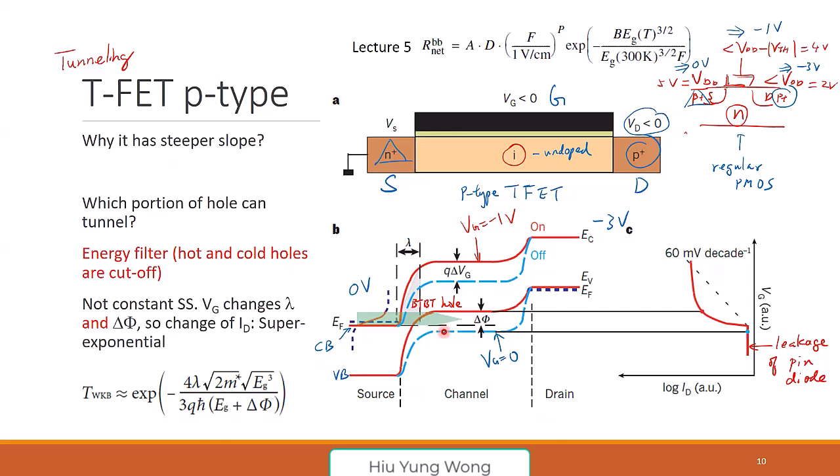Well, there's an electric field. Yes, electric field, exactly. Let's assume the electric field is also very high. Do you have band-to-band tunneling in this case? I believe so. You believe so. But band-to-band tunneling is from where to where? Can you repeat? From which band to which band? From valence to conduction. Or in this case, from conduction to valence band, right?